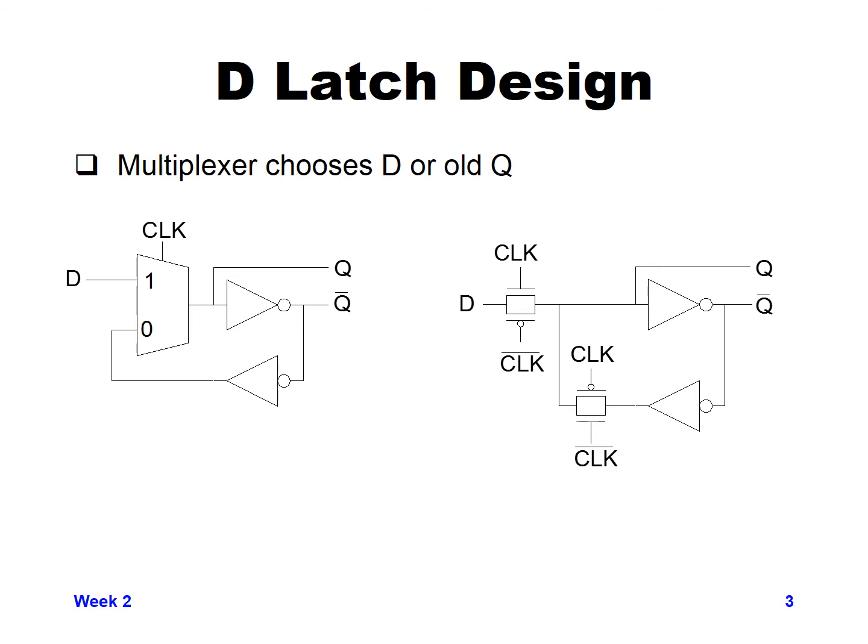This function in transistors, the way you see in the circuit on the right, is kind of the lowest transistor count to produce that function, rather than using a 2-to-1 mux that would be, for example, a 2-to-1 tri-state inverting mux followed by an inverter.